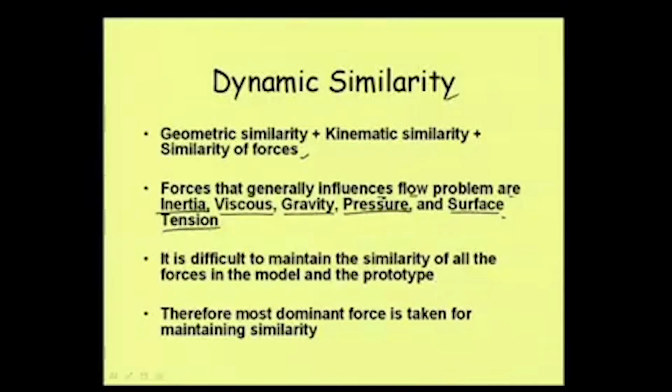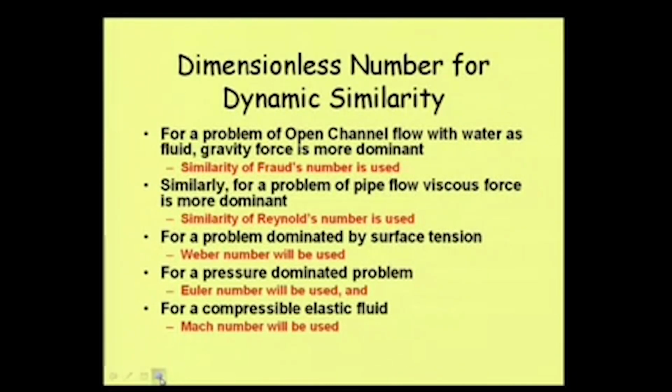Well, so therefore, the most dominant force is taken for maintaining dynamic similarity, basically we are talking about. Then let us see for what sort of problem, what sort of similarity we need to maintain. Say, for a problem of open channel flow with water as fluid. Why are we saying water as fluid? If we talk about viscosity or a viscous fluid, then this may not be valid. But for an open channel flow with water as fluid,